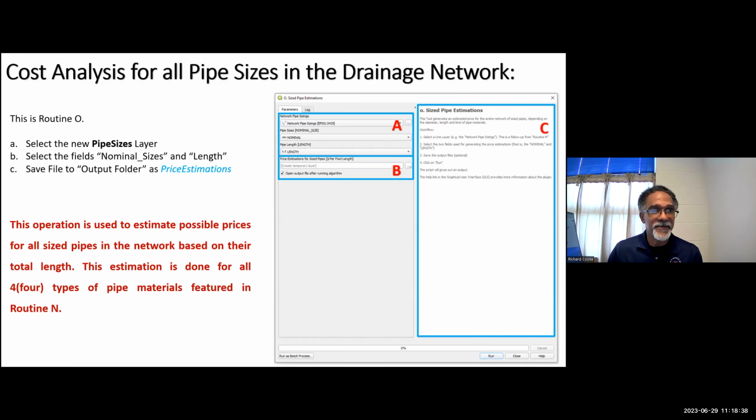After the pipe has been sized, the next thing it does is determine a cost of the system based on a pipe size pricing table. The pipe size pricing table will use NRCS average estimates, the NRCS cost share price for installation for tiles of various sizes, which might vary a lot from one contractor to the other.